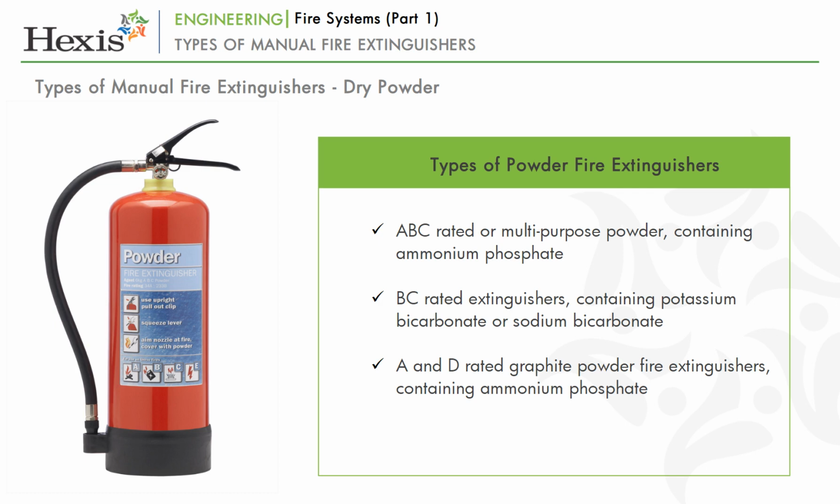The disadvantage of using this extinguisher is its danger of corrosion if the powders are not removed immediately from exposed materials. Monoammonium phosphate is especially likely to form phosphoric acid. Residual powder may cause loss of electrical conductivity as the powders are non-conductive.